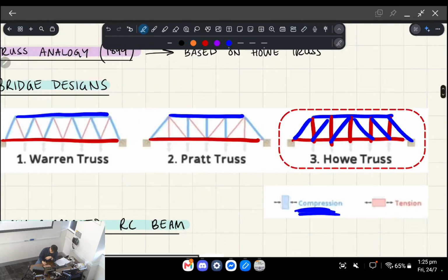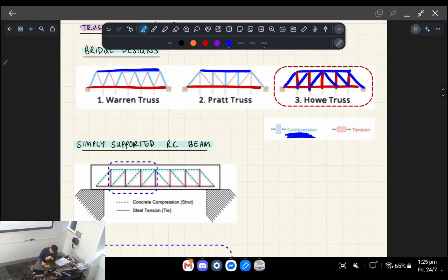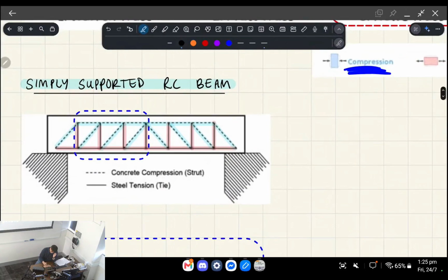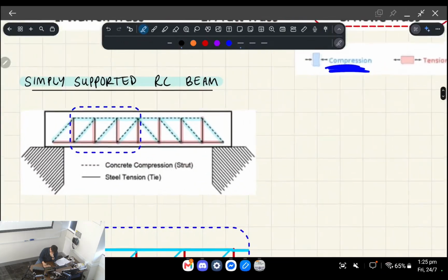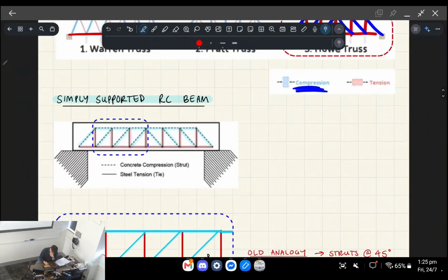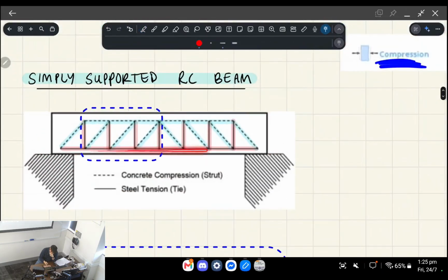So this is basically how we represent a reinforced concrete beam, right? Okay, so there you can see it in terms of, you've got the longitudinal bits of steel, right? So if I drew this sideways, rather a cross section of it, let's say we're cutting there. The longitudinal reinforcement up here is in compression, and the longitudinal reinforcement down here is in tension.